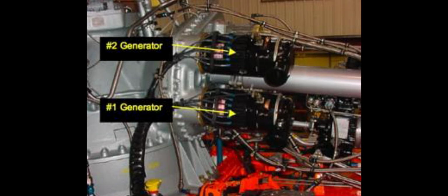The switches are marked on, off, reset, and test. Placing the switches to on will connect generator power to the appropriate bus. Placing switches to off reset will take the generator off the line. If a temporary overvoltage condition occurs, placing either switch in the off reset position, then to the on position, will bring the generator back online. The test position is used for generator maintenance checks.